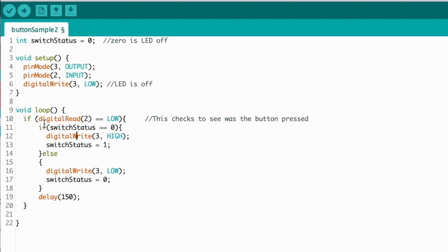So it's constantly looking to see, did we press the button? Remember, that's how we trigger our initial if. Was the button pressed? It's asking that question about 30,000 times a second. When you press the button, it feels like you just pressed it once. But because it's reading so quickly, it will read an unintentional 5 or 10 or 30 or 50 presses of the button when you think you've just pressed it one time.